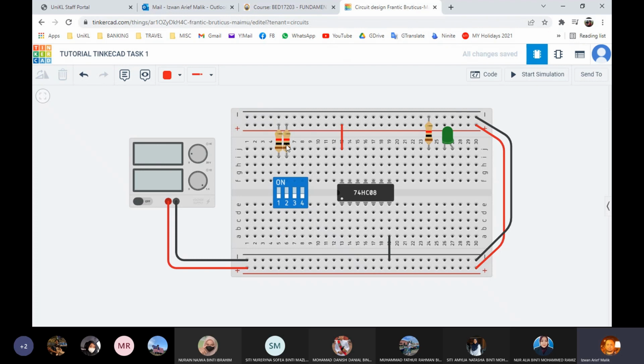So these resistors are used to limit the VCC before it is used by the switch, so that the switch does not get damaged or burnt. So this is VCC, it enters here first and connects directly to pin 1 and pin 2. So we will use these two. And then we need to ground them as well. So we ground it.